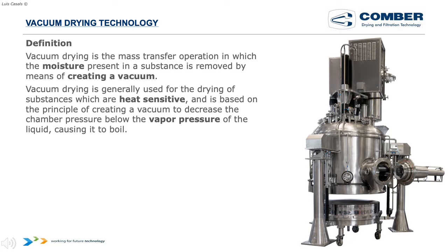Vacuum drying is a technology focused on removing moisture from a heat-sensitive solid by creating vacuum, decreasing the chamber pressure below the liquid vapor pressure. The liquid simply boils. This is how we separate a solid from a liquid.